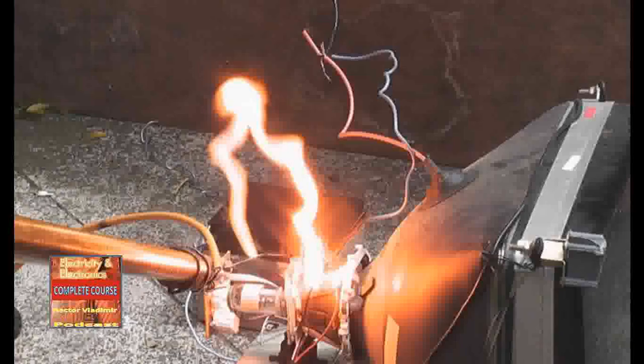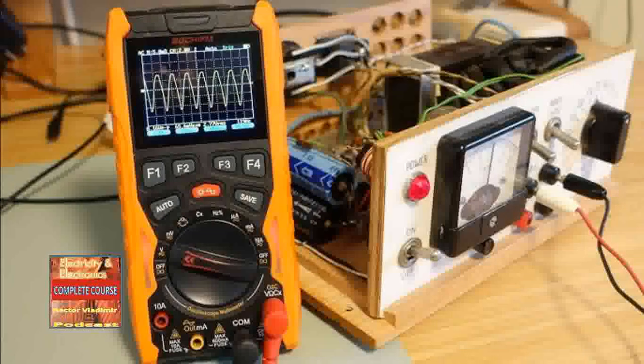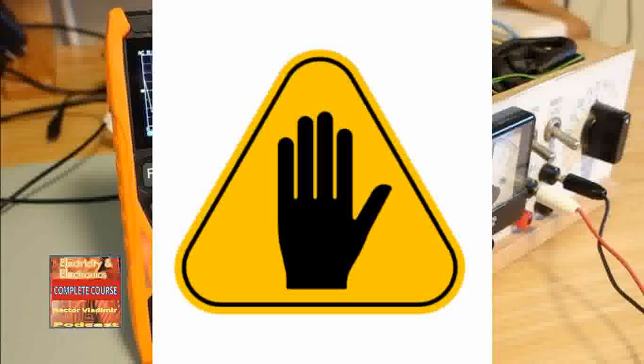You may have selected the correct mode of operation using the selector switch, but left the test lead plugged into the wrong meter jack. It is very important not to attempt reading from the back of a television picture tube or a computer monitor. There are extremely high voltages present in these locations, and the meter usually requires special high voltage test leads specifically designed for this purpose.